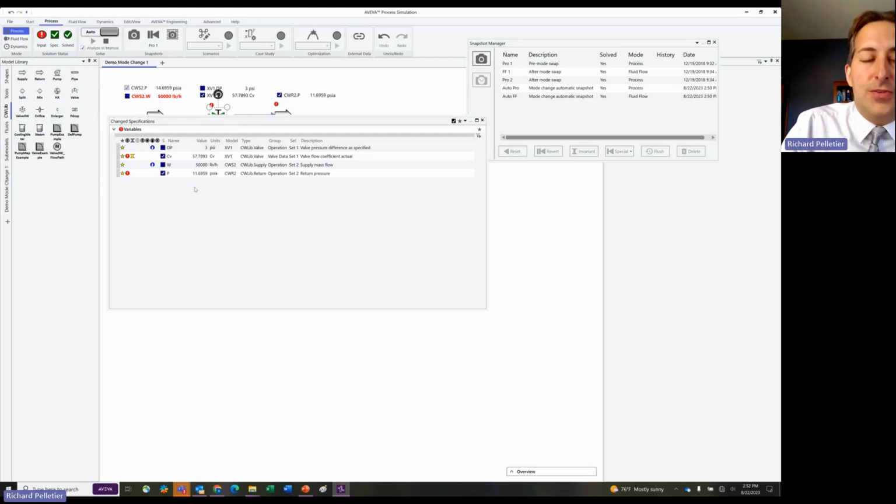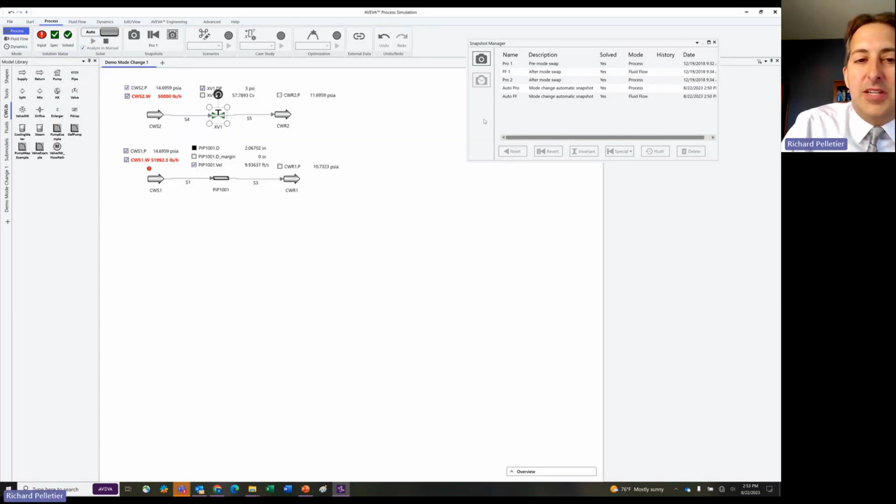This is actually a lot more useful than it might sound in my little quick explanation. And normally in a full training class, I would pull out a demo that shows me troubleshooting a customer file using this. All right, so this is a very useful capability to be able to troubleshoot your convergence. One very easy thing you can keep in mind is that if you revert all of these back to their default, you are very likely to be square and solved, right? In many cases, right? Depends on how far you deviate in terms of the values.